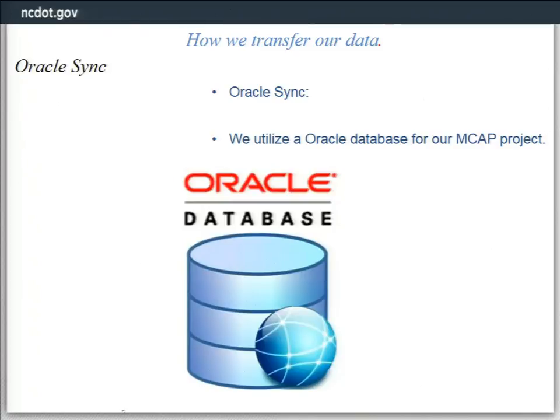Custom Microsoft Access Sync is used to pull the DBF data from the ArcPad checkout into the Oracle database. The sync process requires the MCAP person to be at an NCDOT facility so they can access the secure DOT network. So you can't do a public sync or from your house or anything.